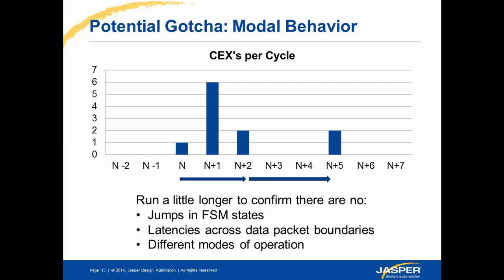So these are in the proof core or the fan-in cone of the property, and you need to run it to a depth of at least 32 or 34, whichever is the suggested depth by the tool, to get more confidence in your bounded proof. If you run it to the depth of 32 or 34, does it mean that there are no more counterexamples?